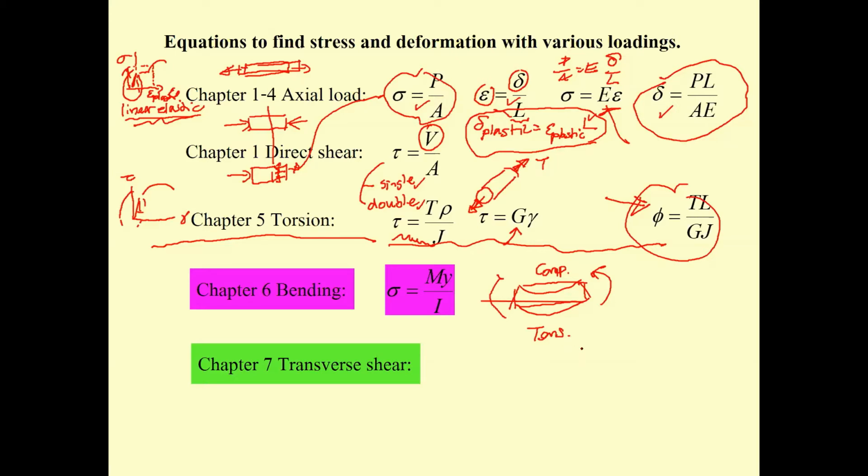If this one is reinforced concrete, you know that concrete cannot take the tension. When the beam is in positive moment, you have to put the reinforcement on the bottom side of the beam. However, if the beam is subjected to the negative moment, this one is going to be in tension and this one in compression.